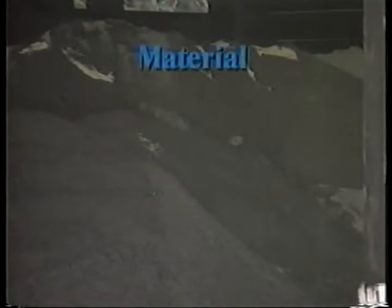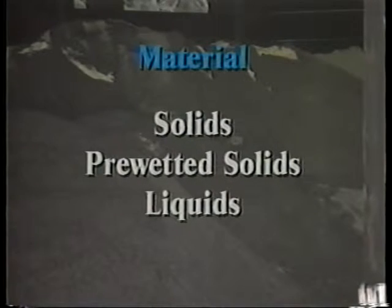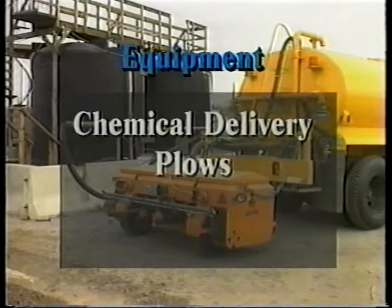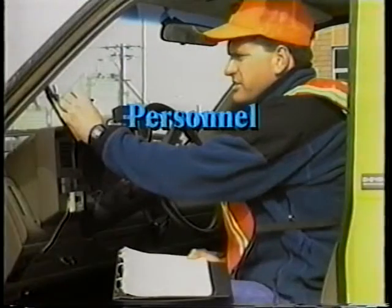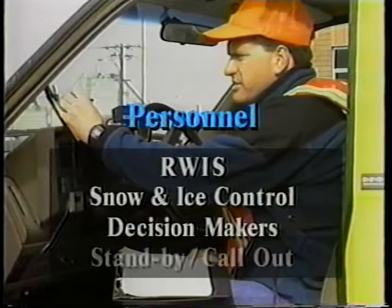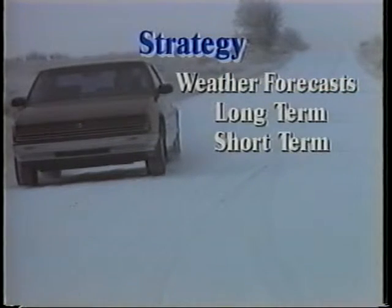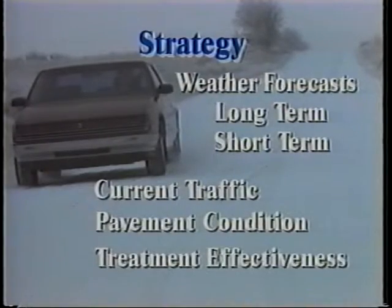Many tools are available to the maintenance manager for anti-icing. Tools for operations include the solid, pre-wetted solid, and liquid chemicals necessary for preventing the ice-pavement bond, equipment for delivering the chemicals at appropriate rates, plows with effective cutting edges, and chemical preparation and storage facilities. Personnel tools are the people skilled in the use of road weather information systems, snow and ice control equipment, technology for decision-making, and personnel standby and call-out procedures. Decision tools include long to short-term weather forecasts, real-time data on traffic, pavement condition, and treatment effectiveness.